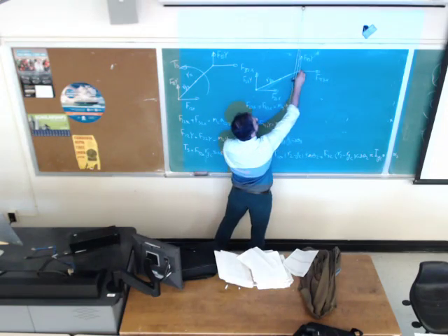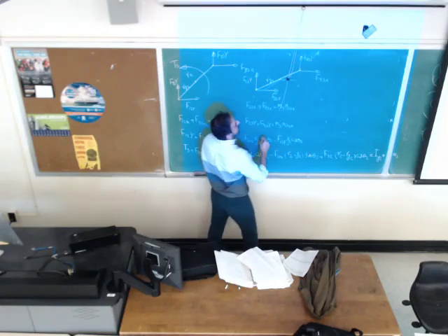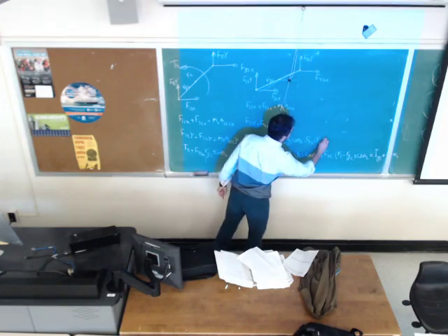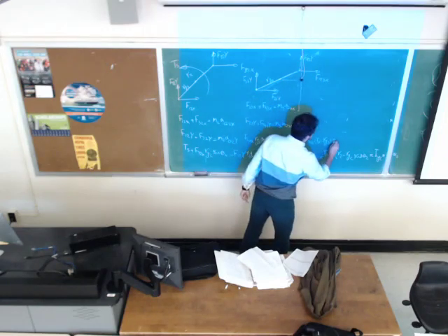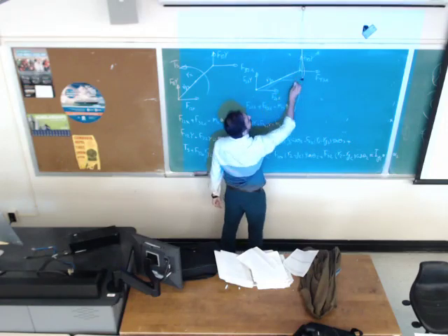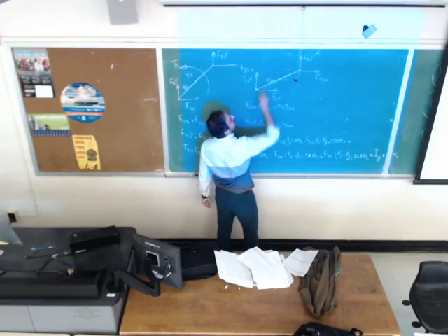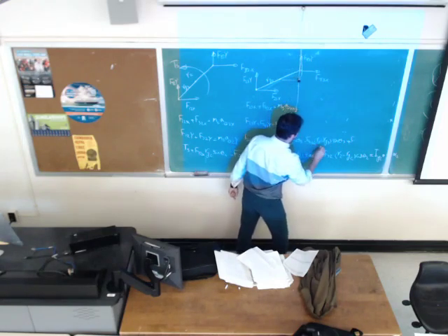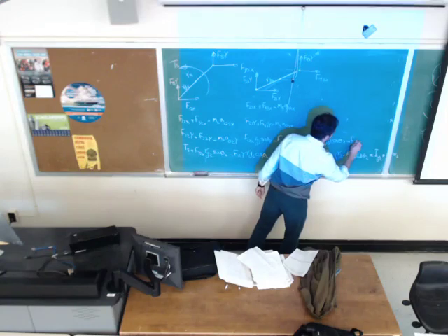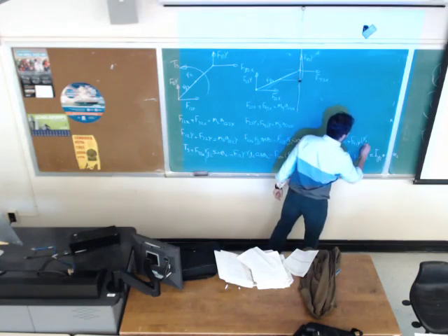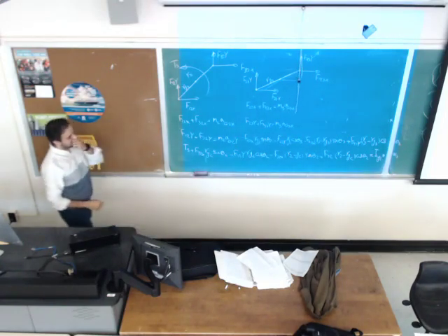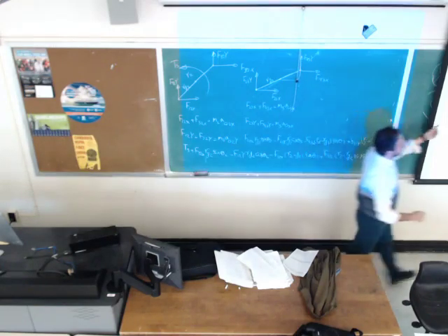This force times this distance is making clockwise, so I put negative F43x times R3 minus RG3 sine of theta 3, and this force times this distance is making moment counterclockwise, positive, F43y times R3 minus RG3 cosine of theta 3. So 3 equations for link 3.